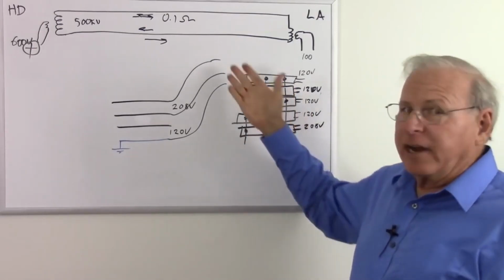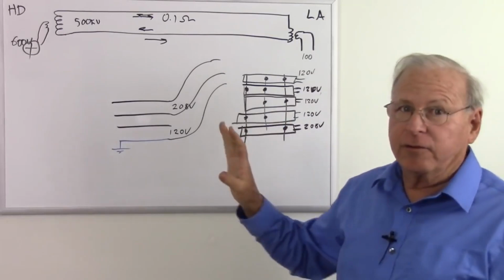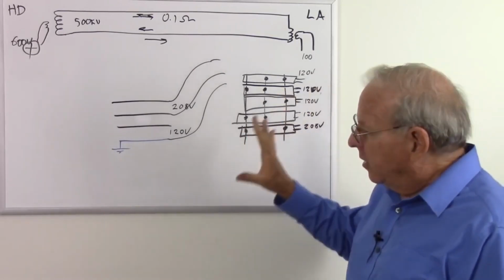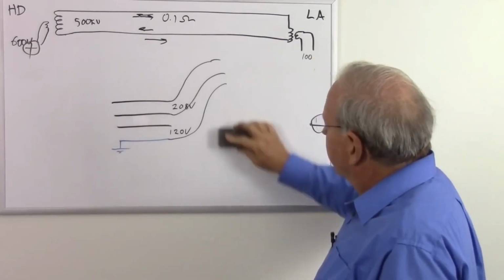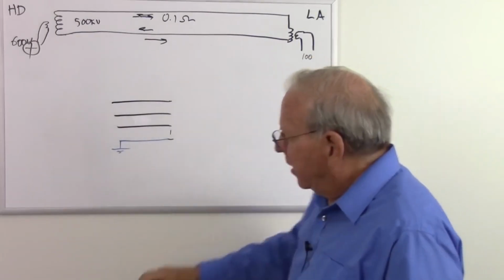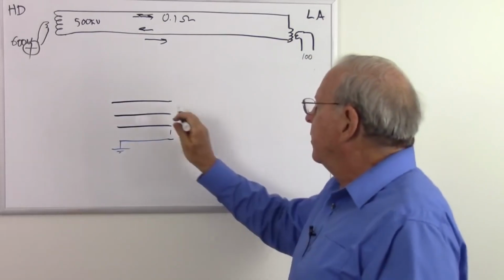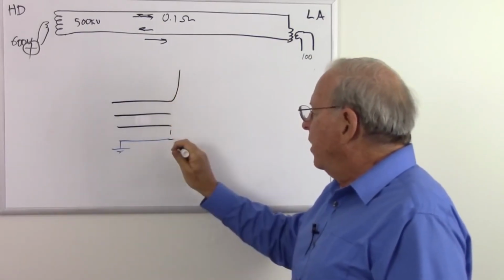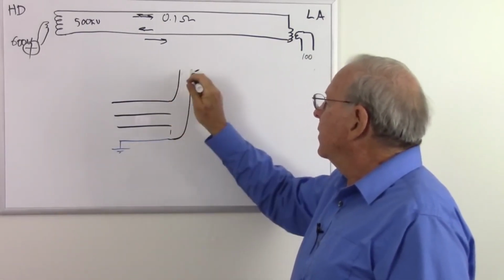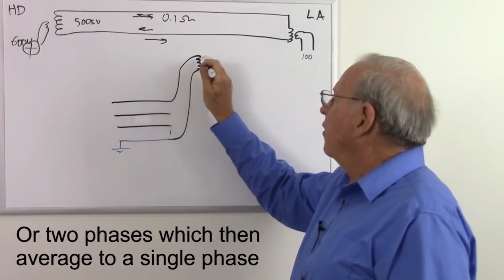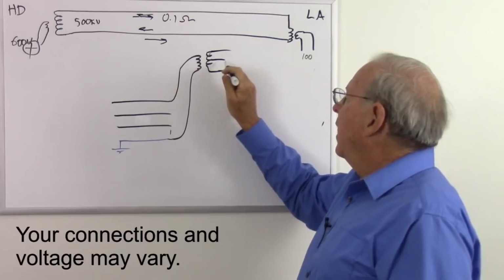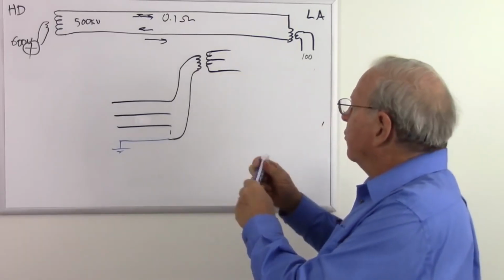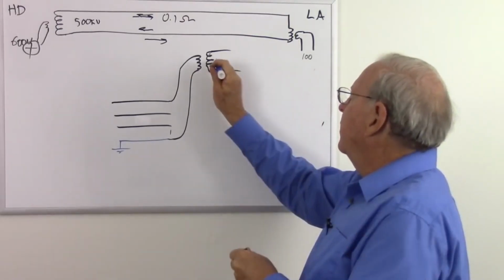Now, I actually lived in a house that was wired like this, and I used to think it was the norm, but apparently the norm is actually to take a single phase into a neighborhood. So here come the three phases into an industrial neighborhood, and they'll take one of those phases and the neutral, send that through a transformer, and come out with a new neutral, and that of course will be grounded somewhere. I'll make this blue because I can.